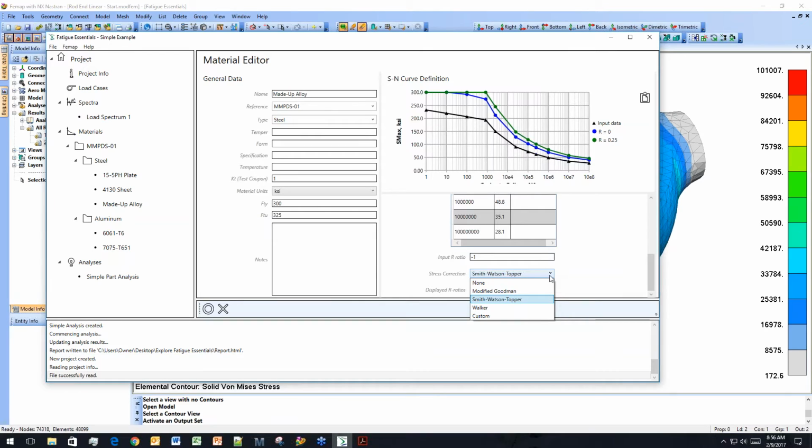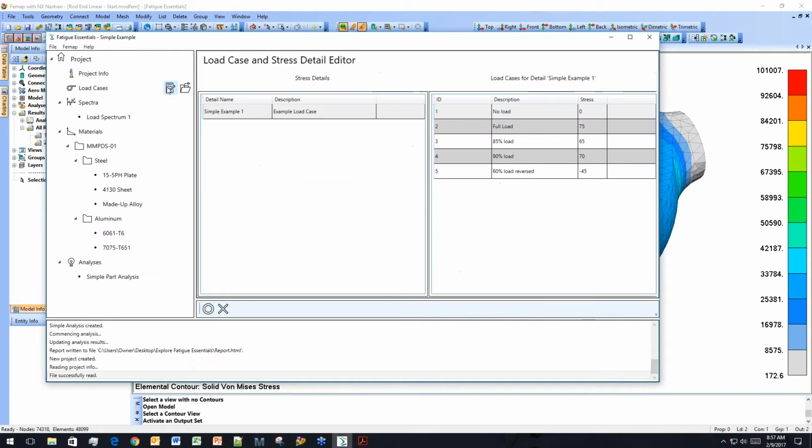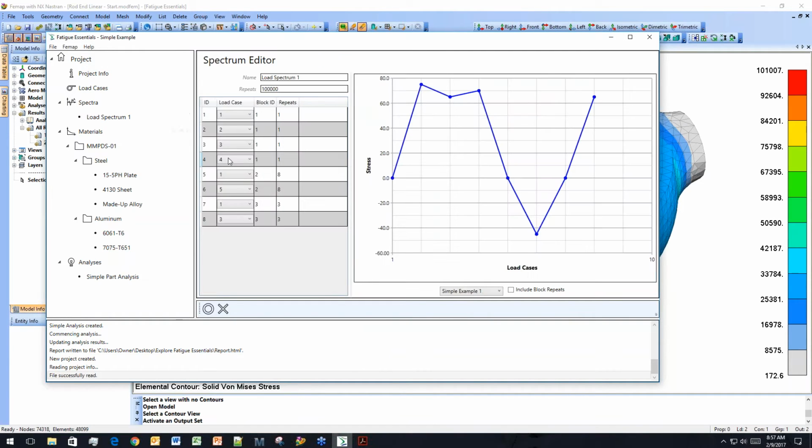And then Kyle, just a reminder as you go through to make sure you highlight the ways that you can import the loads and spectra from a file as well as typing them in. So, I'll let you go back with that now. Good reminder on that one. Yeah, so I showed copying and pasting from Excel into our load and spectra. You can also click this button to load the data from a file, and you can bring it in from a CSV file there. That way you don't have to type it out like I did here.